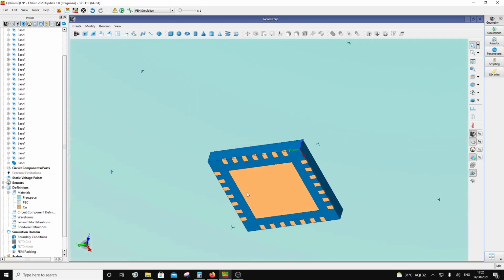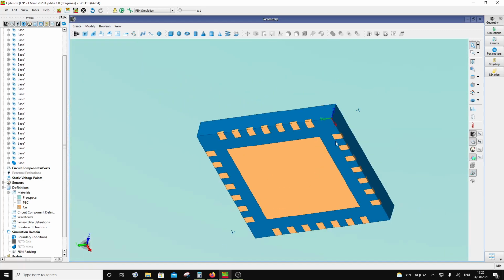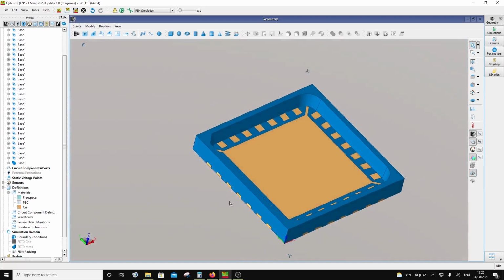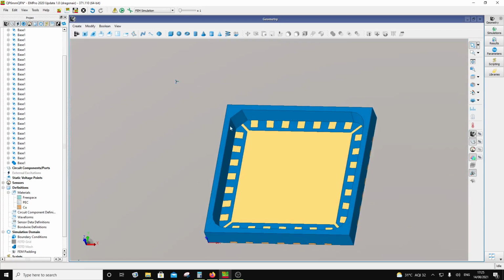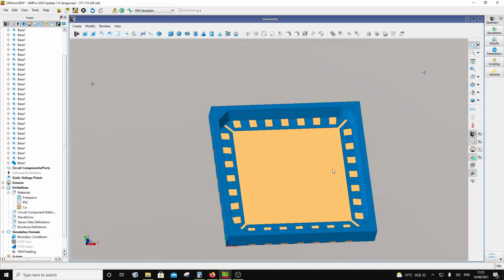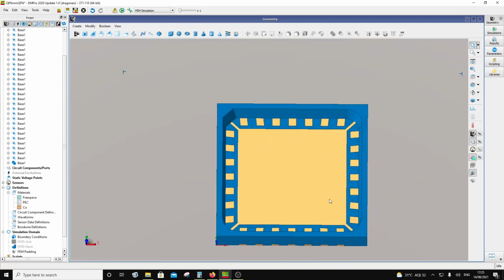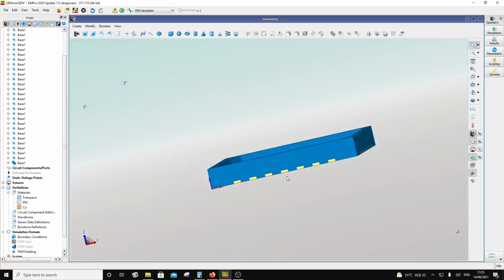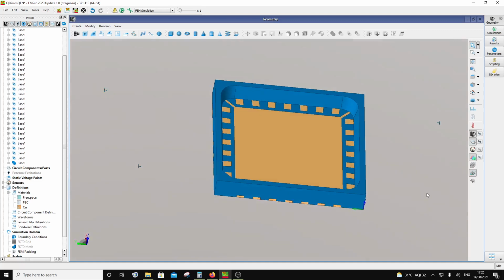And so I have copper contacts, 28 of them, 28 pins, ground pedestal, right? And then I have got these contacts. Now I'll be able to put my IC on top of it and then put wire bonds here, right? And then below this, I will be able to put my board, whichever board or laminate I use, and that will be it.